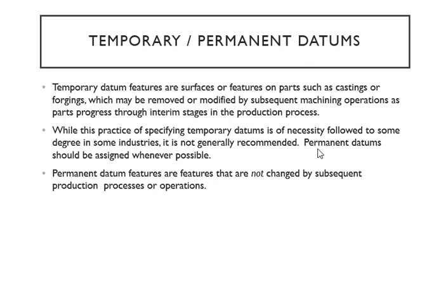We want to deal with the permanent datums more than the temporary ones because it's a lot of work. But of course, in some industries it is necessary, depending on the product and how important that is. If it is needed, do it. If you don't need it, don't waste your time on it. Permanent datums are features that don't change in your production process.